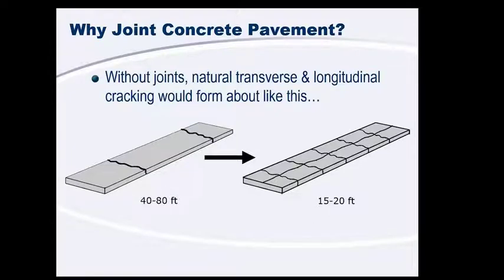That initial crack helps alleviate the initial buildup of stress. But as the life of the pavement moves on, the stresses continue to build up, and eventually you get cracks about every 15 to 20 feet in both the longitudinal and transverse directions. All of that helps alleviate the stress that has been building up through all of those forces we just talked about.